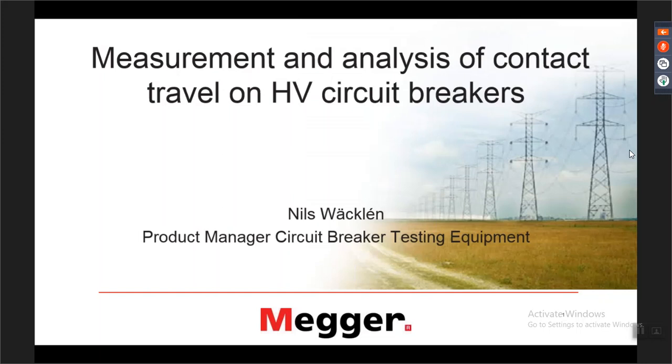So why do we want to measure contact motion? There are several reasons for that, and one is to apply to standards. I will come to that later. Another is to obtain important information about the circuit breaker and its condition, as part of the maintenance program or a maintenance strategy, and collect data for future trending analysis.